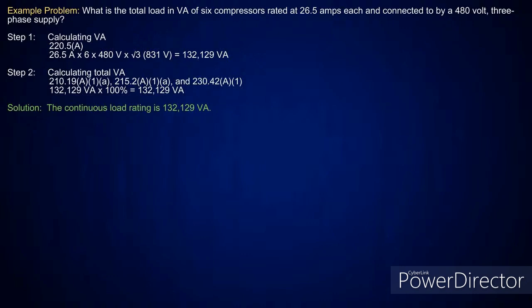Because when I get to the end in my 7th calculation, I'm going to take between my refrigeration motors and everything else, and whichever is the largest motor load is going to be the one that gets the additional 25% applied to it. So this keeps you from getting screwed up. Just do everything at 100% on these compressors and motors. So I've got 6 of them here.